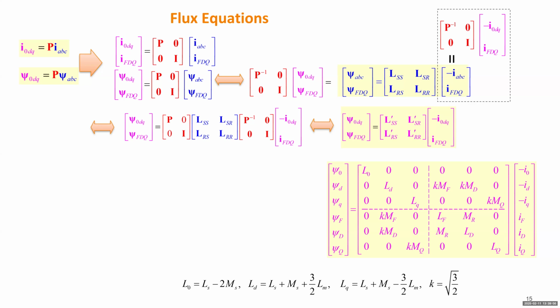Okay. So a round rotor generator has one additional winding. ABC will be the same, but for this psi FDQ, you have to add another one. You call it Q2, or maybe use a different letter. This flux linkage vector and the current vector will become 7, so we will have 7 elements. And this matrix is also bigger. The matrix will not be 6 by 6, it will be 7 by 7. You have to do that in the first homework.